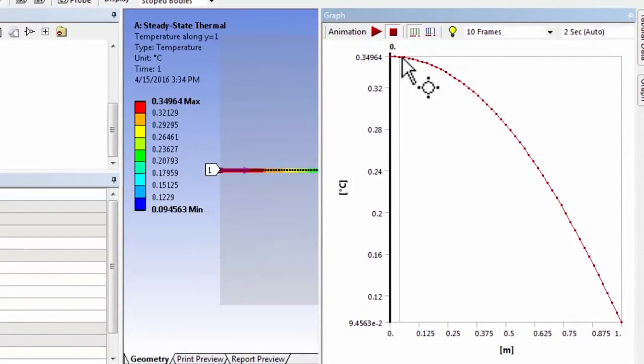And it also gives me a graph, and this slope has to be 0 because that's an insulated boundary. That's dT/dx. The slope is dT/dx, and since it's a natural boundary condition, it won't be satisfied exactly, but it looks like it's pretty good. And you can see here the temperature is quite a bit lower